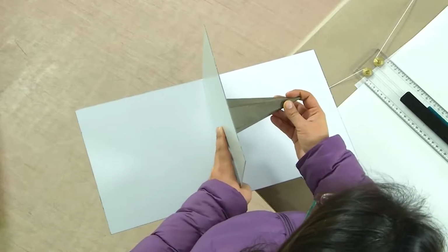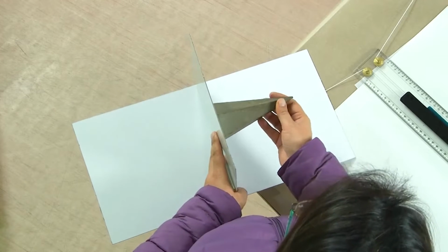Or the other condition could be that this was the original condition where the base was like this, the axis is parallel to HP, and it is inclined to VP. So, we could also have it this way, where the axis is parallel to HP but inclined to VP. In that case, again, we will still see the true height of this solid in HP, but we will see a skewed figure being drawn in the VP. That is what we are going to see.